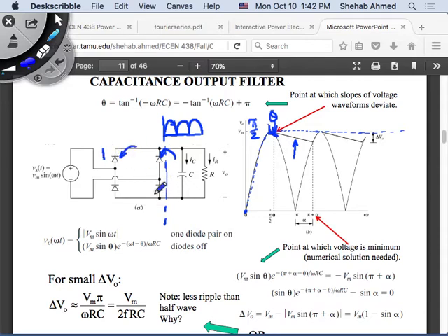So originally diodes 1 and 2 are connected, and they're charging this capacitor. Then you bring the voltage down, it means you're discharging the capacitor. Discharging the capacitor means current has to come out. Current tries to come out, the diodes block it from coming out, and they disconnect. That's if I don't have a resistive load.